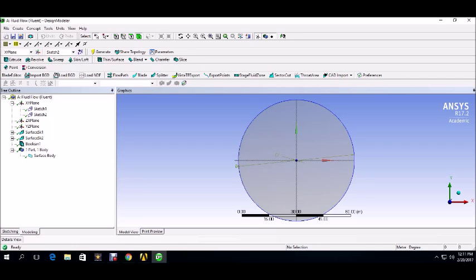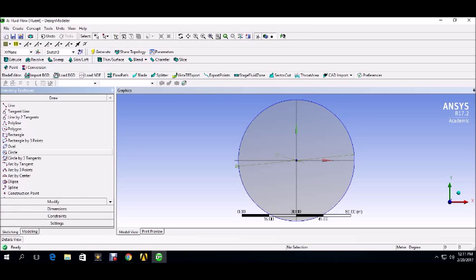Okay, next step, we're going to click on the XY plane, and we're going to make another new sketch. You're going to create a line. So go to sketching, go to line. You're going to create a line that goes through the 2 circles. So have it start above and then make it go all the way down below. Make sure your X coordinate is at 0 when you stop and finish.